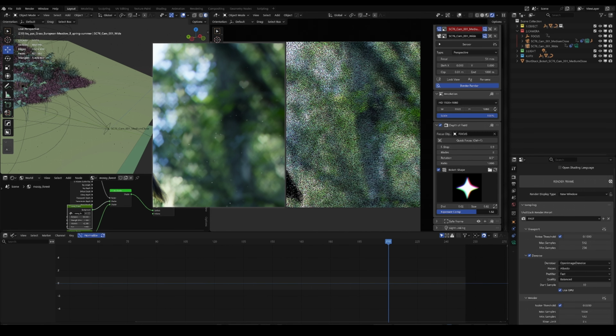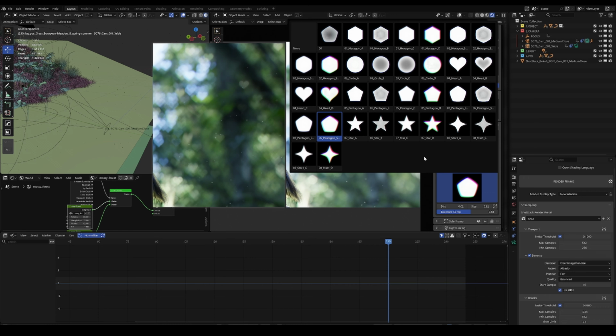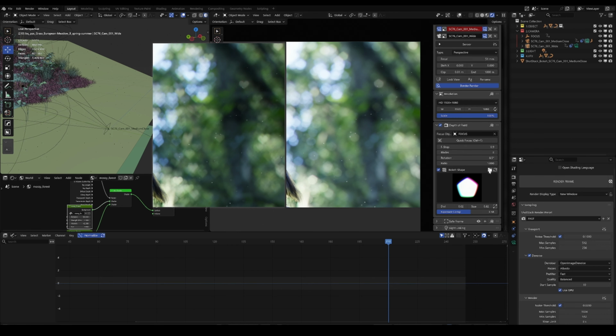Besides using the built-in aperture shape library of the plugin, you can also easily design your own customized aperture shapes. You can create an image with a black square background just like the one shown here, and then simply draw the exact shape you want right in the center. Next, open and import the shape you created by dragging it into this folder. Then click refresh, and it will appear right here in this list.